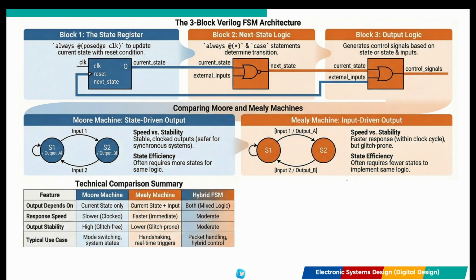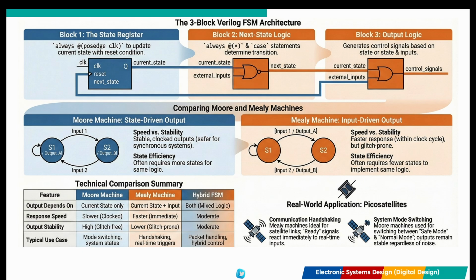Before coding, FSMs are mapped out visually to understand the required flow. Nodes represent the states and directed arc arrows represent the transitions. Moore outputs are written inside the state circles, while Mealy outputs are written alongside the transition arc. These look similar to a software flowchart. They use state boxes to denote states, decision boxes like a diamond to evaluate input conditions, and conditional output boxes like the oval for Mealy outputs.